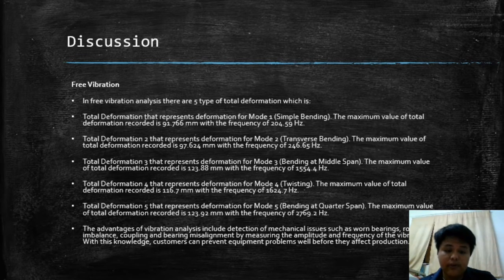The advantage of this vibration analysis includes the detection of mechanical issues such as worn bearings, imbalance, coupling, and bearing misalignment by measuring the amplitude and the frequency of vibration.